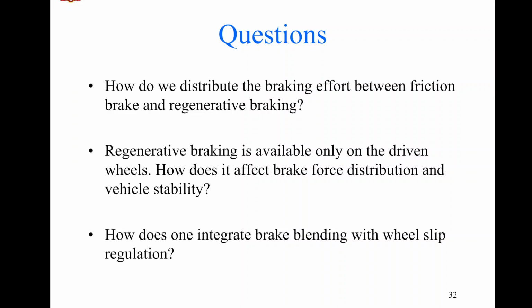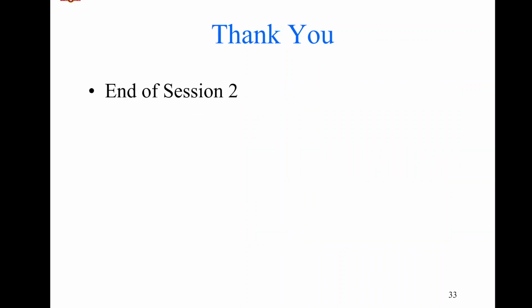The question we are ending the regenerative braking topic with is: how do we distribute the braking effort between friction brakes and regenerative braking? The second question is how does it affect the stability of the vehicle, and how does it integrate brake blending with wheel slip regulation? We will discuss what wheel slip regulation is during the discussion we will have on braking aspects.